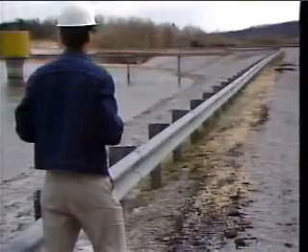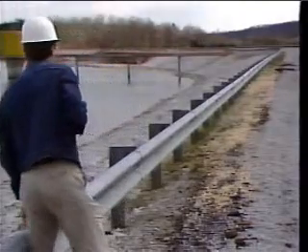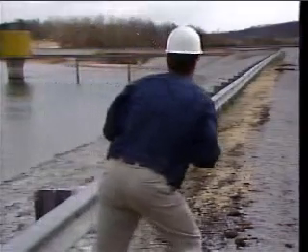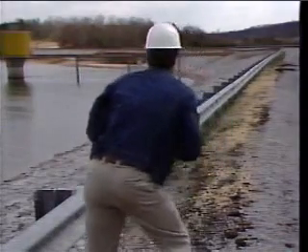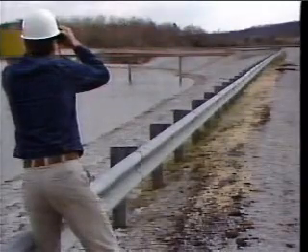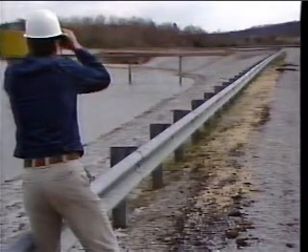A useful sighting technique when checking the crest and slope alignment is to center your eyes along a line of markers and move from side to side to view the line from several angles. These markers can be guardrails, posts, pavement stripes, or parapet walls. As mentioned in the text, what you're trying to do is discover any misalignments and irregularities along the crest and slopes. One technique you might find very helpful is to sight along the line of markers with a pair of binoculars.